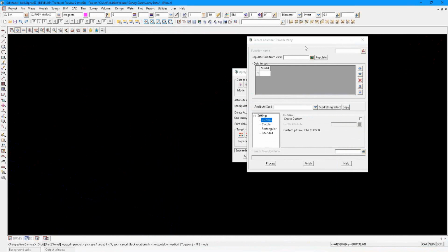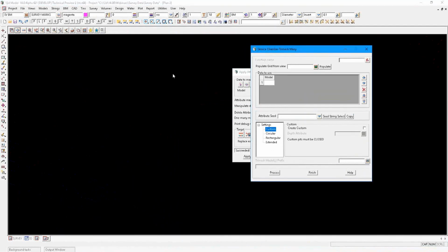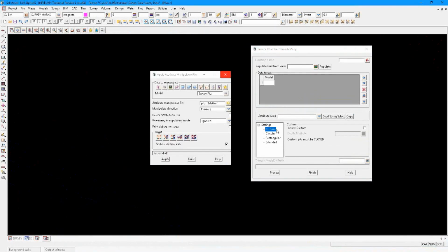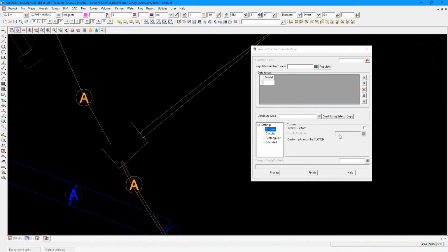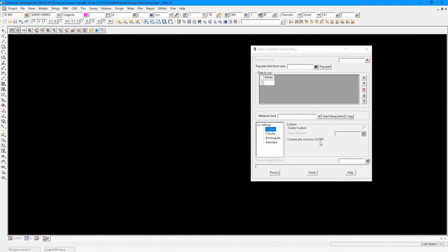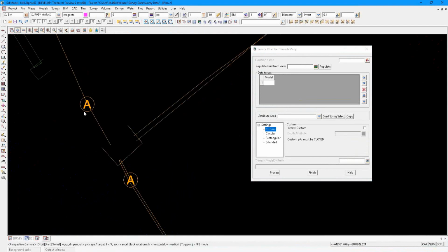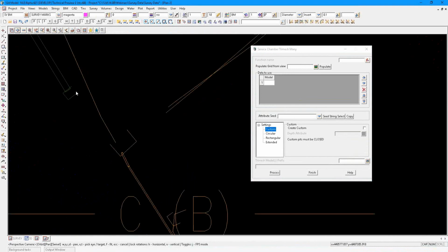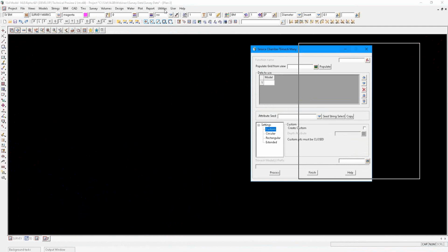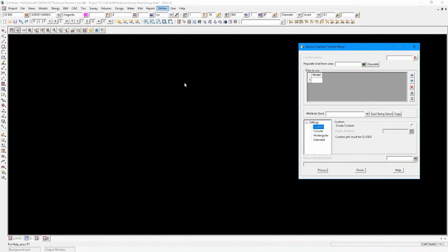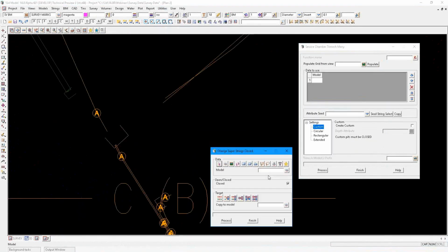The other thing that this panel requires is that for custom pits, so where you've surveyed the top of a pit, and it can be any shape you like, custom pits must be closed. Okay, so all of these strings where the surveyor has surveyed around the top and hasn't closed the strings, we can now globally close those. So under utilities, A to G, close.